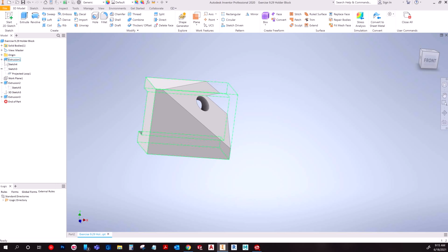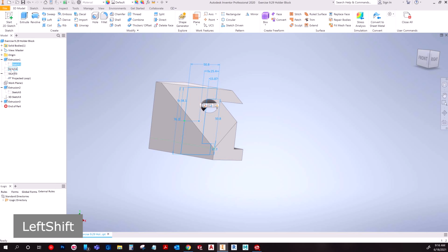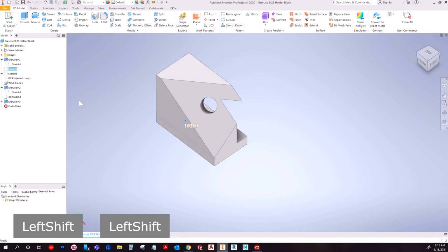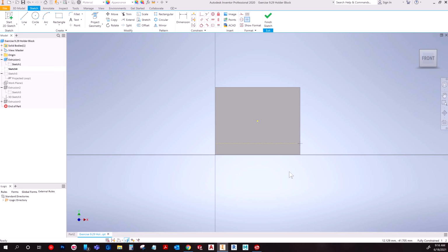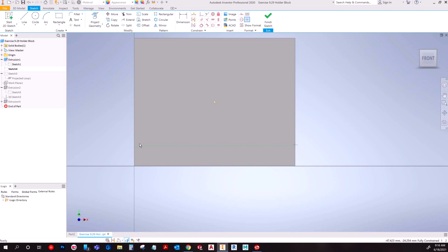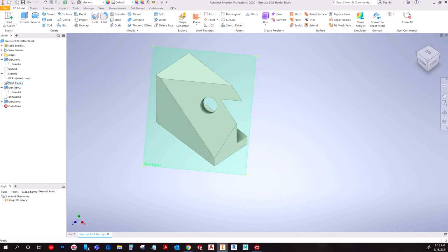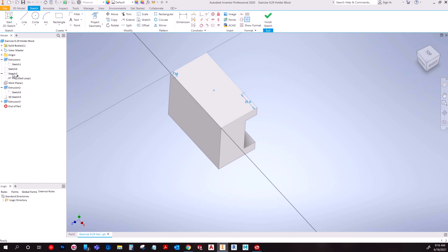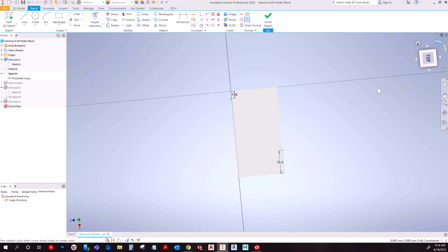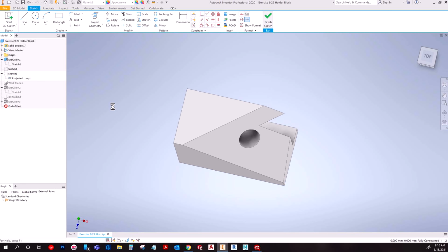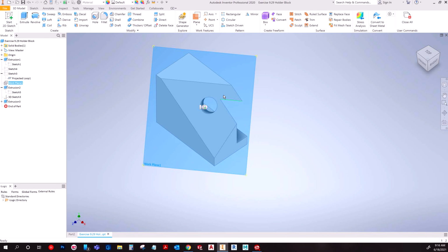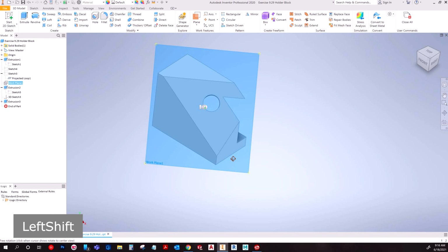But all I did was make my normal part shape right here, and then I made, I can't tell what the sketch is, I keep looking at it. All I did was project this edge, and then I put a point. That gave us one of the 3 points we need for a 3-point projection. Then I did the same here, making a point where I knew the values. Then I just made a plane that touched those 3 points, and then I was able to cut it away.